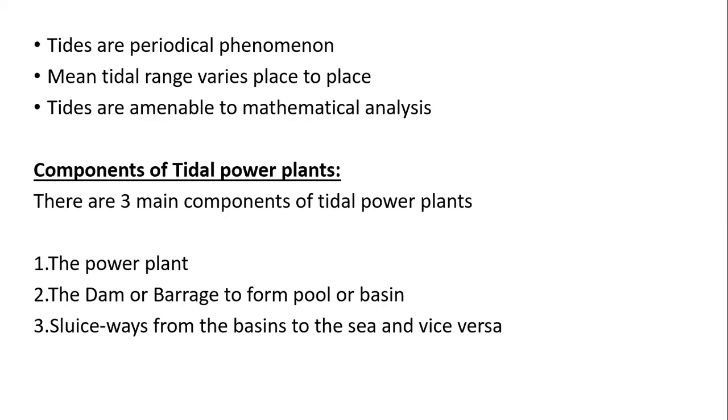In a year, the tides at the time of vernal and autumnal equinoxes will be even higher due to the relative location of the sun and earth. We discussed the equinoxes before. At the time of these equinoxes, we get higher tides compared to other days. The tidal range shown in the figure varies from time to time. Generally a long-term mean value of R is designated as the mean tidal range at any particular point. So this is the first point we have to note.